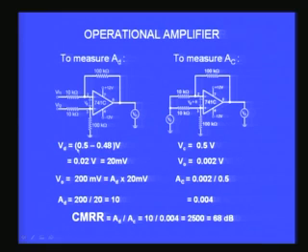So, what is the differential voltage? 0.5 minus 0.48, and that is 0.02 volts, or 20 millivolts. So, the differential voltage at the input terminals of the differential amplifier is 20 millivolts, and the gain is 10 here, 100K and 10K. Therefore, the output voltage, if I multiply by 10, will be 200 millivolts. AD into 20 millivolts is 200 millivolts.